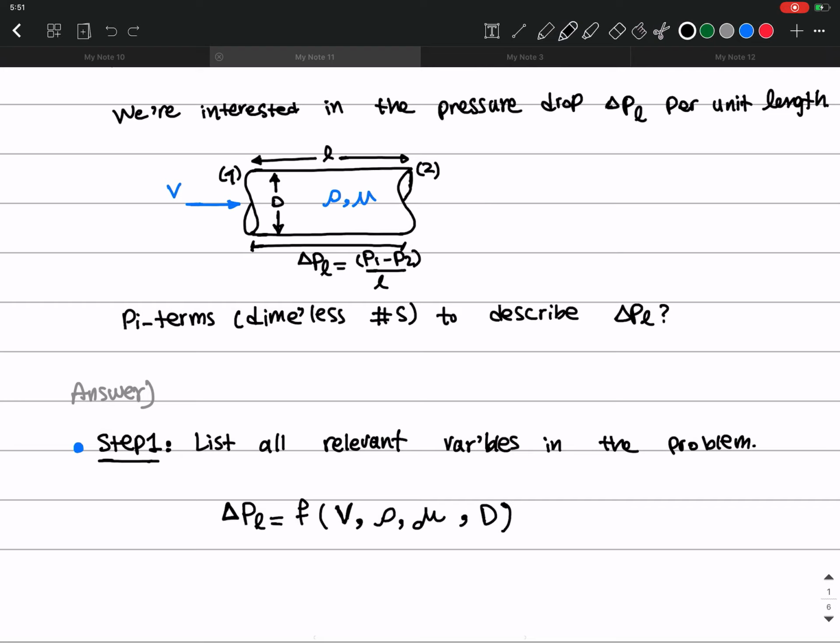You can write it down and you get a parameter, but when you do it in the lab, you will see, oh, the effect is not that important. Or you can say the viscosity of air, like it shouldn't matter, right? Because the flow is inside the pipe and it could be water or oil. So the density of that fluid is more important.